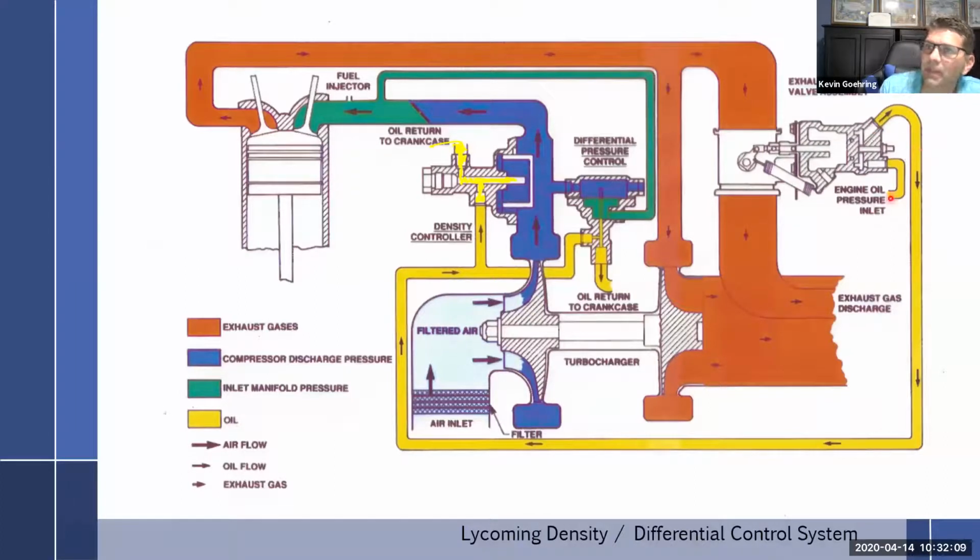But if I have oil coming through here, and right back to the engine, how much pressure gets built up here? None. Exactly. No pressure gets built up here. And if no pressure gets built up here, then this doesn't do anything and it stays in the open position. And if it stays in the open position, that is turbo off. Off. Okay.